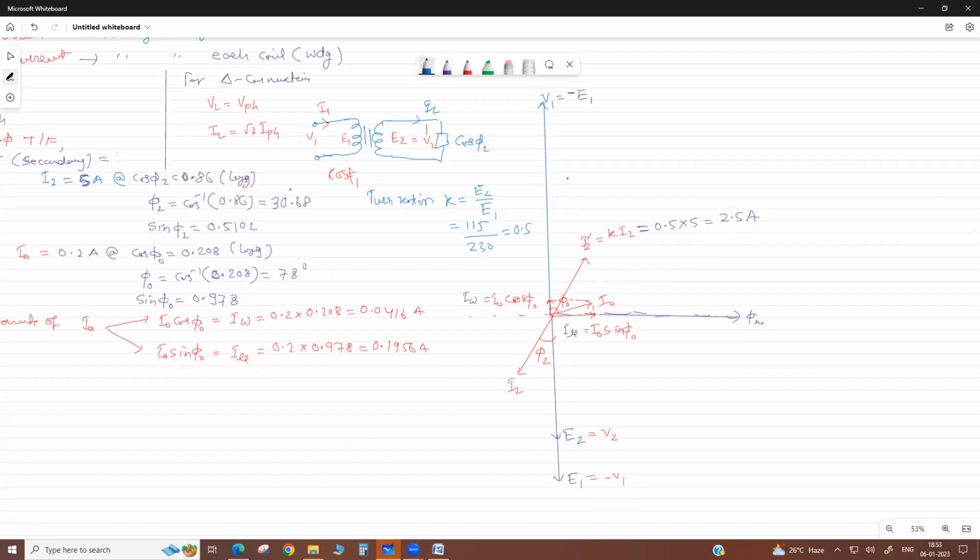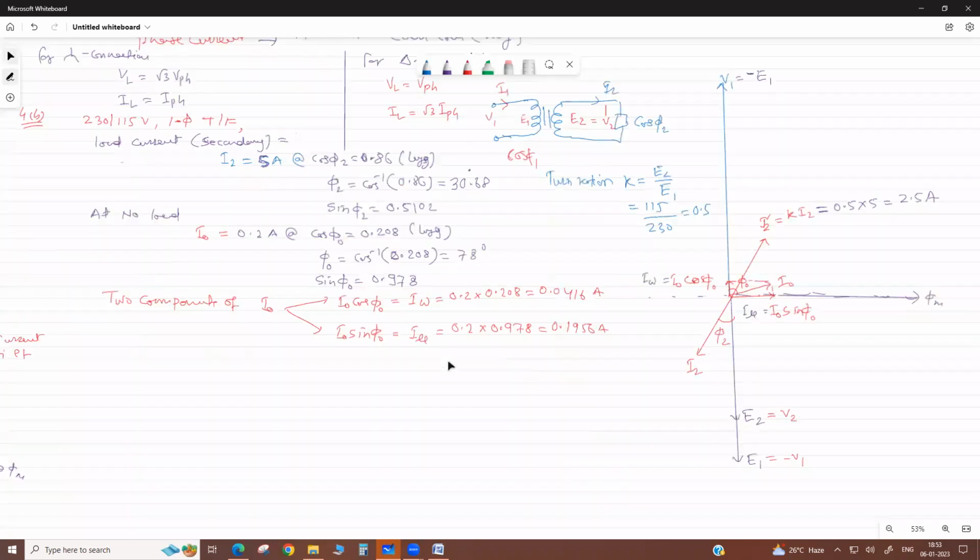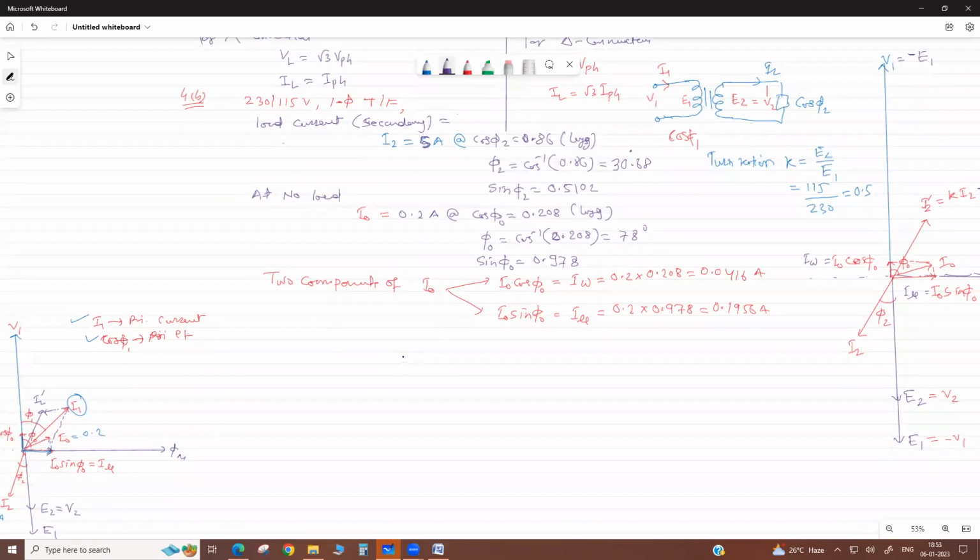Then you know now this is primary voltage. As I told, at load condition, if we see in the equivalent circuit, correct na? See, suppose this is your magnetizing branch here. Okay, this is your load side, secondary side. Here we apply the voltage V1. Then there is an I1 current. At this node, there is an I0 no load current, and here it is I2 dash as referred to.